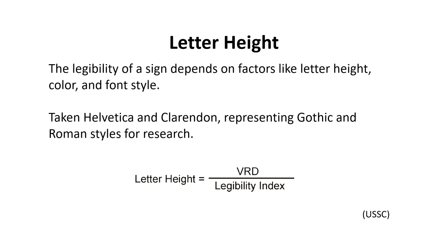Based on that research, the United States Sign Council created the standard legibility index, which shows how far in feet a sign can be read for every inch of capital letter height. The sign legibility index table also takes into account that letter height goes up by 15% when all capital letters are used. We will go much deeper when we go through it.